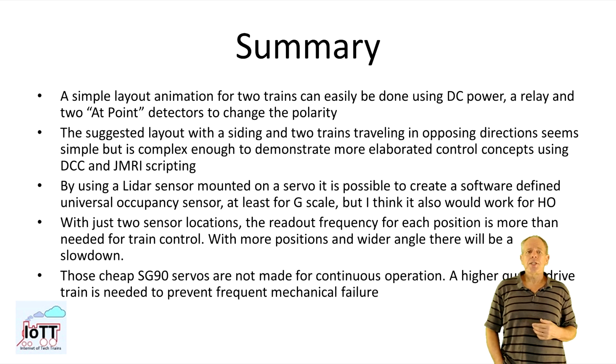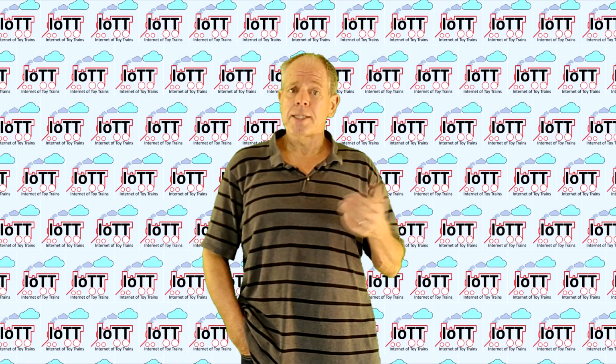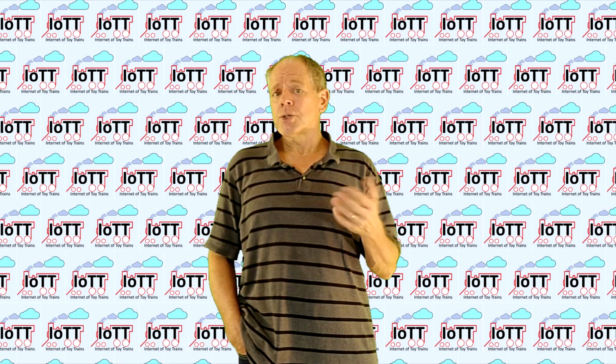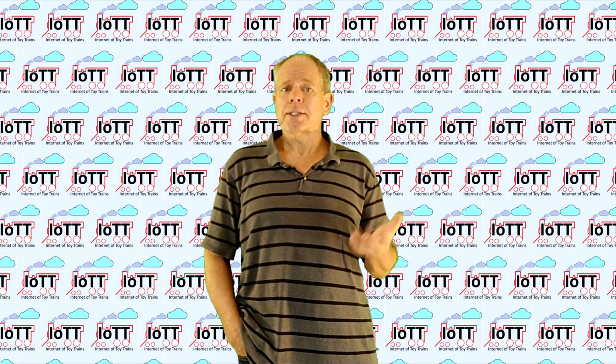Those cheap SG90 servos are not made for continuous operation. A higher quality drivetrain is needed to prevent frequent mechanical failure. Going forward, I will try to have more sensor locations and run the trains using DCC. I will also connect LocoNet to a PC and JMRI to see how the trains can be controlled using scripting.